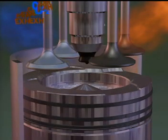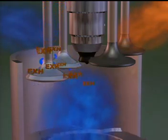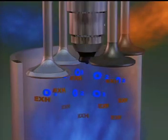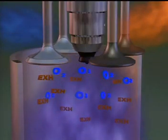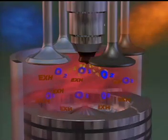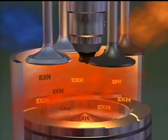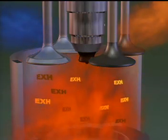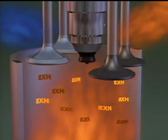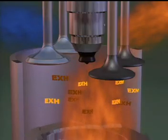The mixture of recirculated exhaust gas and fresh intake air is referred to as the charge air. The extra exhaust gas in the charge air is inert. This means that it has virtually no oxygen in it. Therefore, it will not burn. Also, some of the heat energy during combustion is absorbed by the inert exhaust gas instead of the fresh air, thereby reducing peak combustion temperature. This reduces the formation of NOx while minimizing the use of retarded timing.